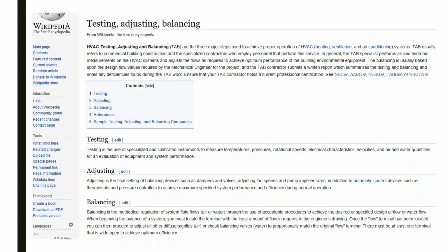If you know that you shouldn't go below a certain point, that's where we get into systems like demand control ventilation. Even that has its ups and downs. It depends on how you measure it and where you measure it. If you measure it at one single point in the building, that's not going to help you. If you measure it in all the zones, that's going to help you, but that's expensive. So that's where you get the trade-offs. You've got to come up with effective solutions that don't cause problems.